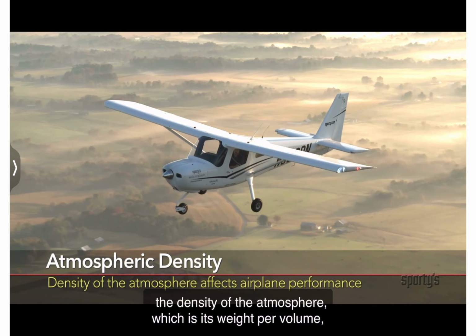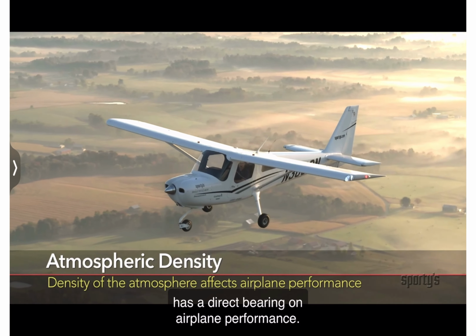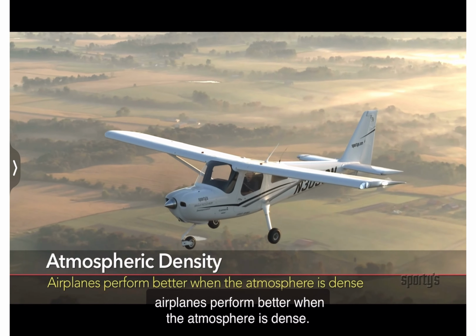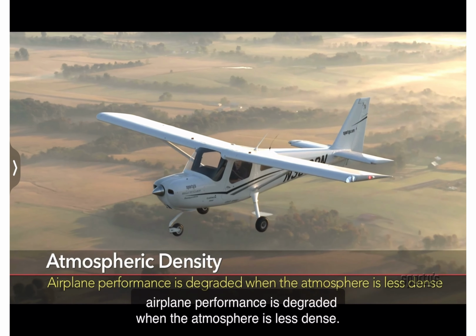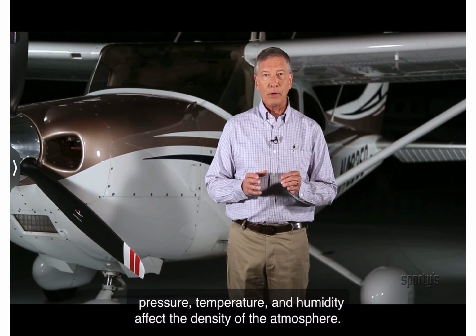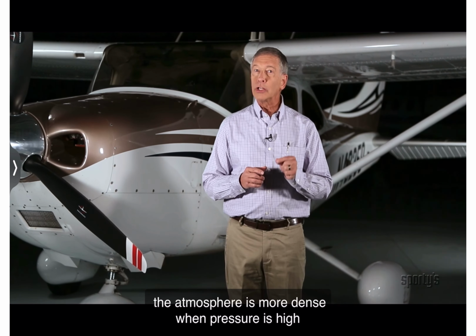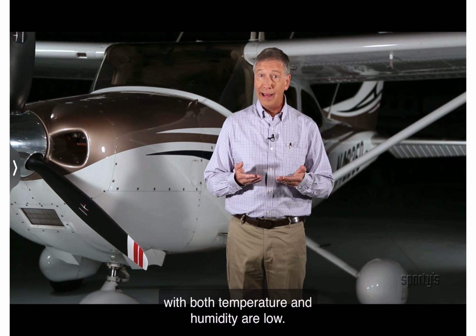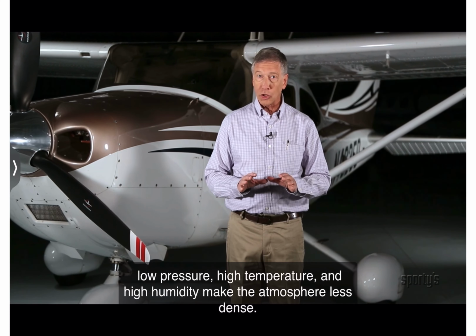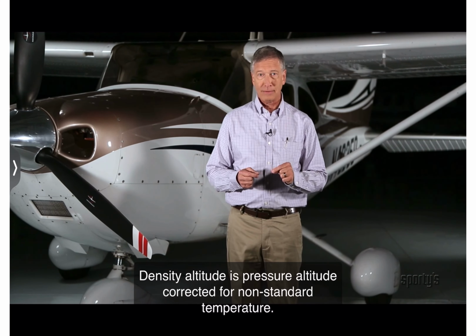The density of the atmosphere, which is its weight per volume, has a direct bearing on airplane performance. Airplanes perform better when the atmosphere is dense. Airplane performance is degraded when the atmosphere is less dense. Pressure, temperature, and humidity affect the density of the atmosphere. The atmosphere is more dense when pressure is high and both temperature and humidity are low. Low pressure, high temperature, and high humidity make the atmosphere less dense.